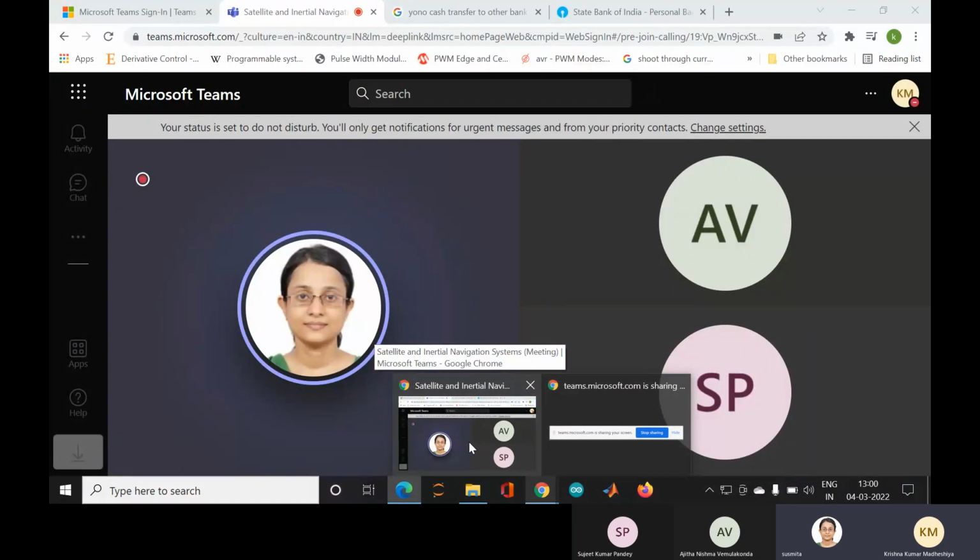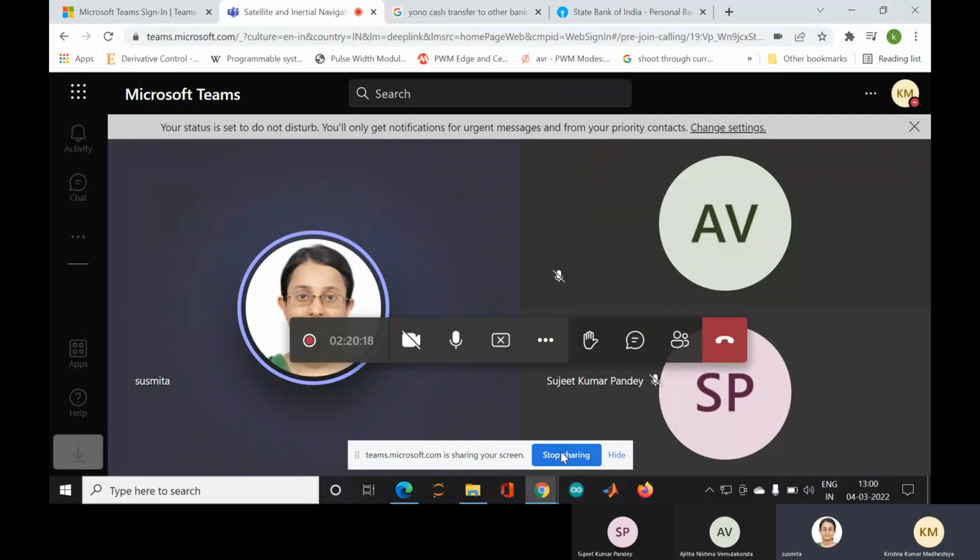I'm telling everyone, this is the best way you can verify whether you have done it correctly or not, because the Kalman filter is a minimum mean square error estimator. And you have a linear problem, so minimum mean square error will also give a linear estimate. The Kalman filter also gives a linear estimate. You should get identical results.